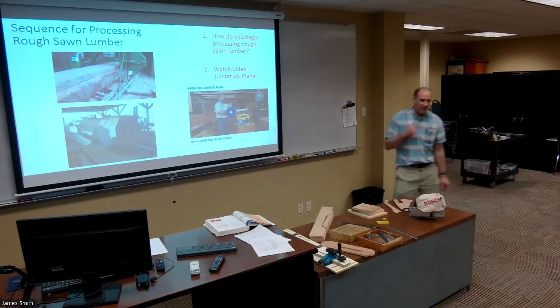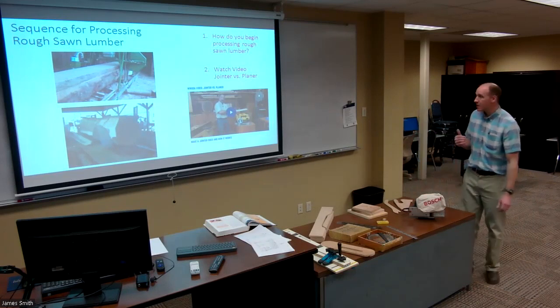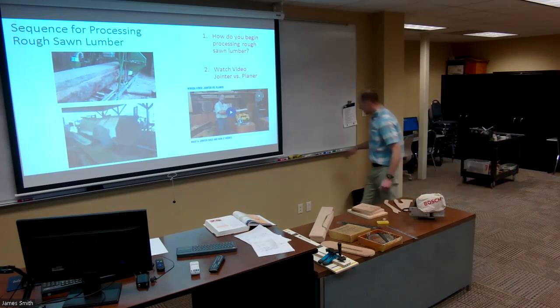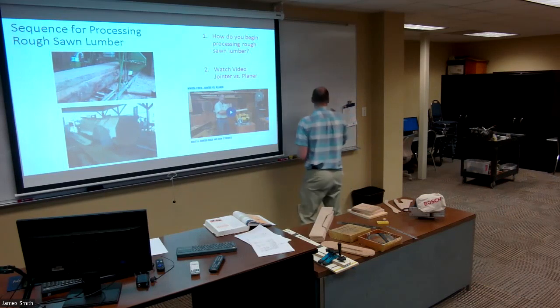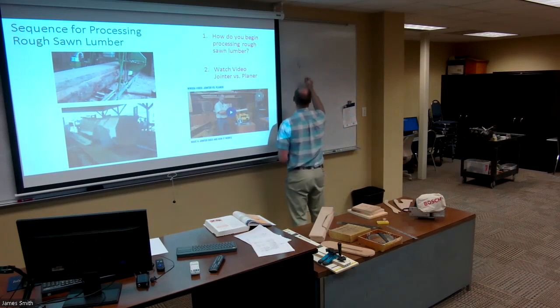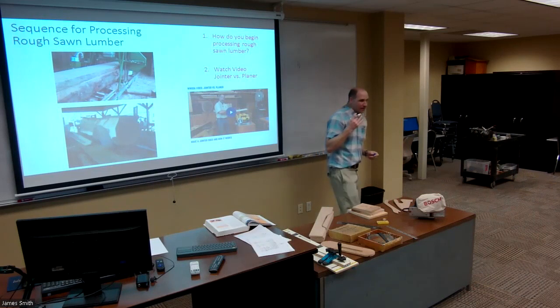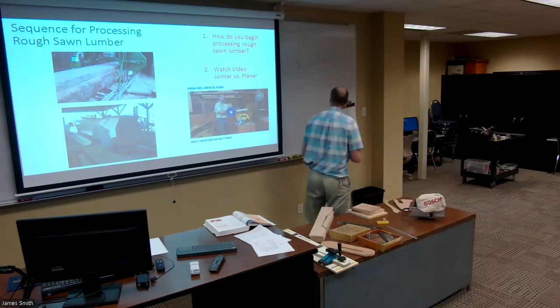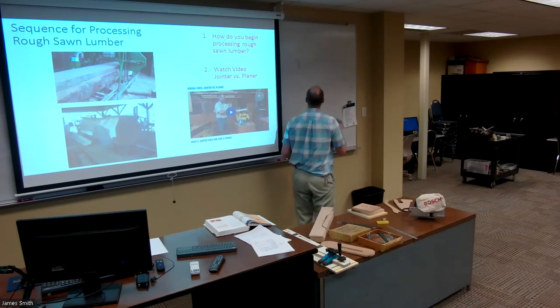And so there is kind of a tried and true process. What I usually do, first things first, is you need a straight edge and you need a flat surface. One thing you never want to do is try to run a twisted board on the table saw. That's just bad news. You're going to get into that, and then it's going to want to rock, and now you're binding against the blade, and it's going to want to kick back, and it's just not a great idea.